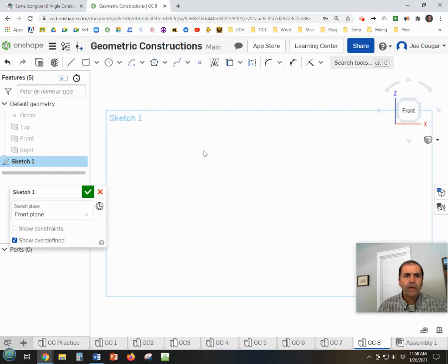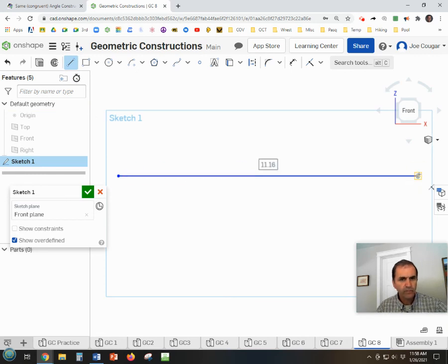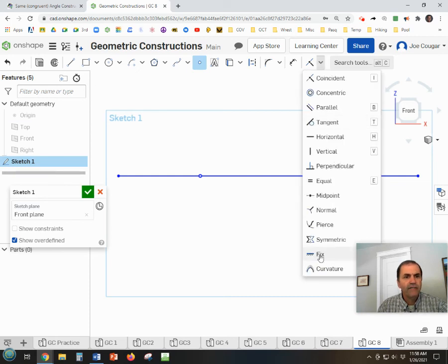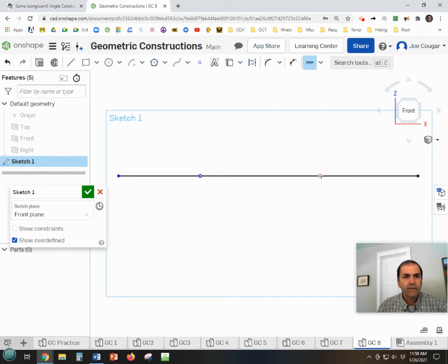Hide the origin. Okay, we're going to start by drawing a pretty long line. Go most of the way across your screen. Go ahead and make that line horizontal, although it doesn't really matter. And we're going to place 2 points along that line. Let's go ahead and go here and here. Now that line needs to extend longer than beyond the points. So basically what we're doing is we're making 2 perpendicular lines through a point. Let's fix all of this stuff by clicking on all points.